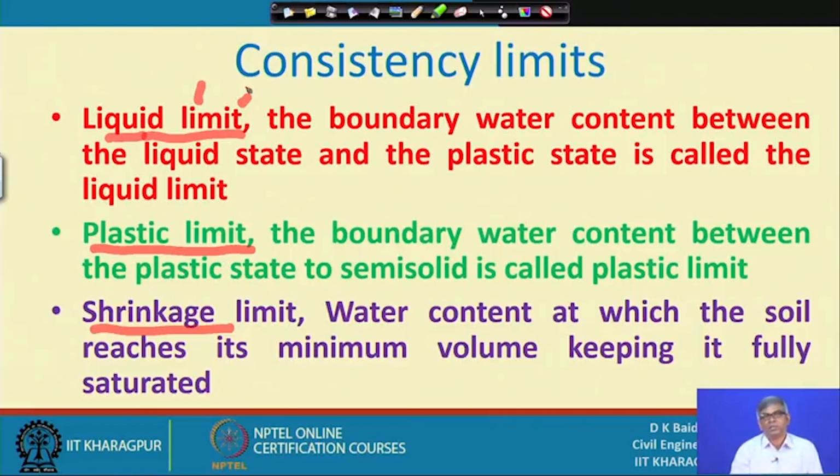And in soil mechanics, this water content determination is a very routine work. Most of the tests we do, we always require to find out water content. For finding out the water content, generally we take a sample in a particular can and take the weight, and then you keep it in the oven for 24 hours at a particular temperature, and the moisture will obviously be evaporated.